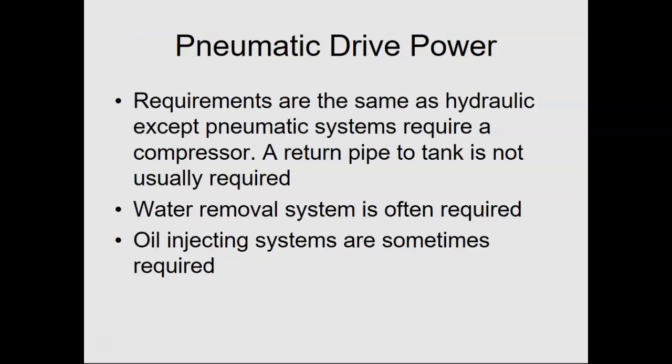Pneumatics, most of it's the same as hydraulics, only you don't have to have a return to anything. But you do have to have a water removal system, especially here in the South. Why? Summer is our enemy here in the South whenever it comes to anything mechanical, especially pneumatics.